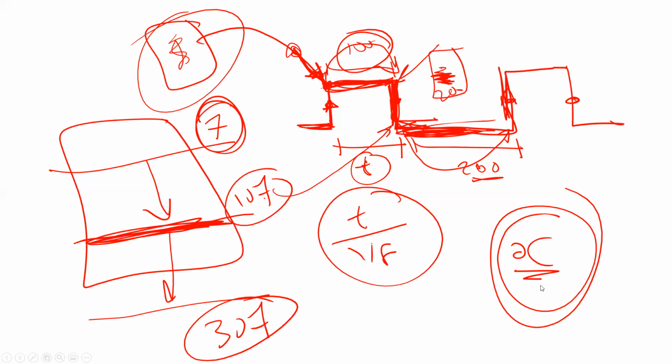So now you can understand why output compare has interrupts. Also, you should understand why the counter is used here, because this time is going to be measured in number of counts. Is that okay, guys? Is that clear? Conclusion: output compare is used if you want to generate a square wave efficiently, and we use a timer here. We have an interrupt here, here, and here. Every time the signal changes from high to low or low to high, you have one interrupt. All you have to do is say how long the signal has to stay here in order to toggle after this time. Okay, this is what output compare is.